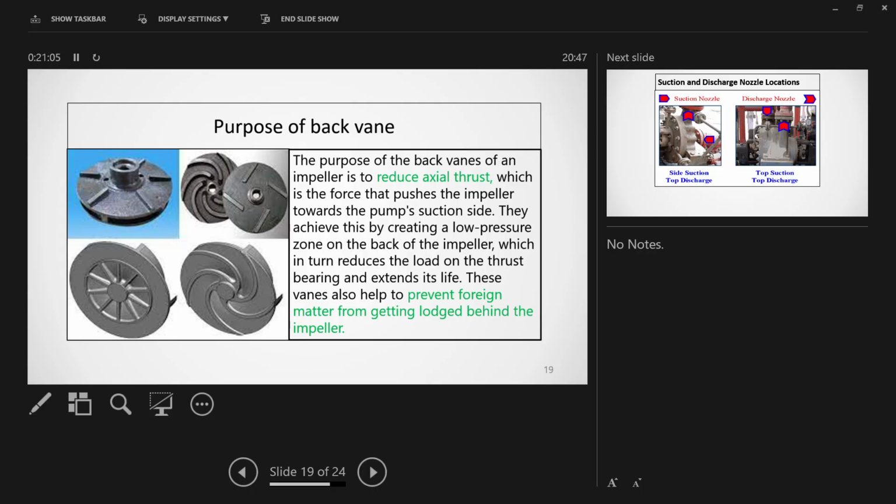We are maintaining a very close clearance with the back plate, and through this hole some suction fluid can also come to the discharge side, and this also plays like an impeller. So fluid will go outside, and it will not allow the discharge pressure to come inside. So this pressure will be less. So axial balancing plus close clearances, recirculation will also be less.